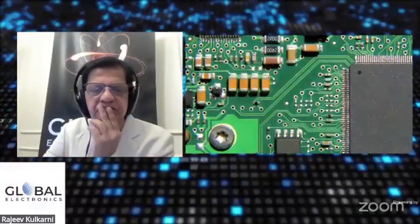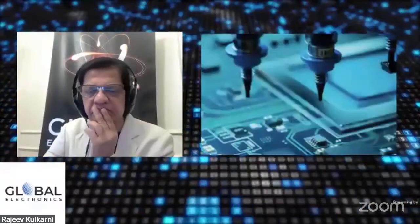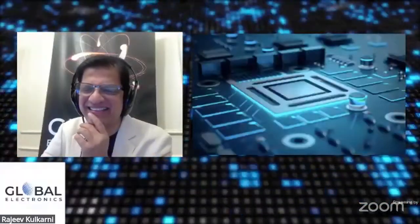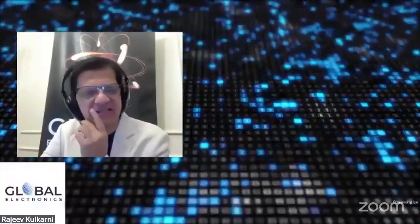My way of getting a wider trace was I always spec for 95 ohms in place of 100 ohms. Naturally, it becomes a wider trace. Now, many PCB CAM vendors told me, I'm giving you perfectly 100 ohms, why are you asking for 96 or 95 ohms? I told, "Boss, this is my way of getting a wider trace. This is another way of getting a wider trace, plan B."